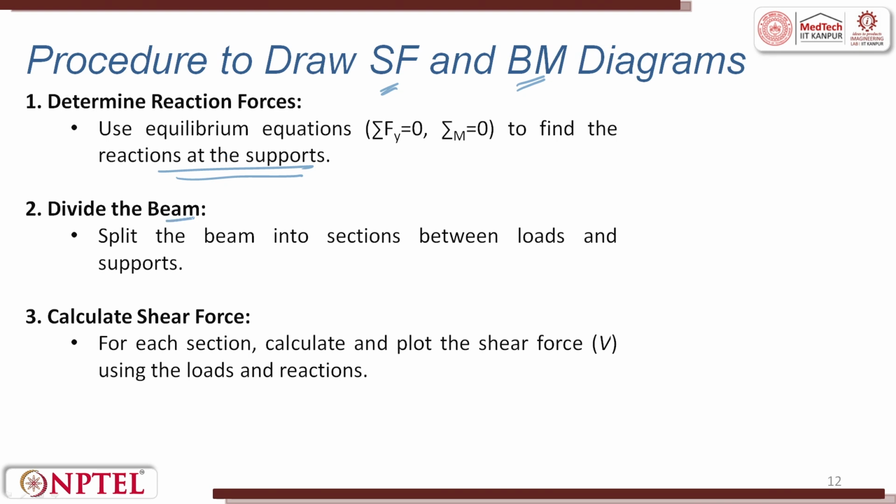Next, split the beam into sections between loads and supports. So, step number 2: first find out the reaction force, then divide the beam, then calculate the shear force.